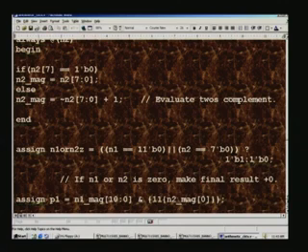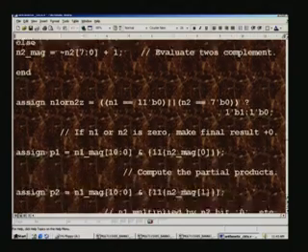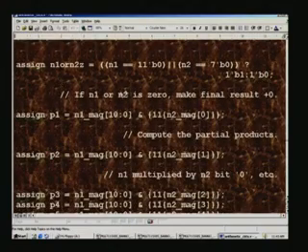And these are all basically combinational circuits, and this is also another combinational statement, wherein we inspect whether n1 and n2 are zeros. Even if one is a 0, the final result is going to be 0, and if you do not take this, you may get into problems later on with the finite fixed point arithmetic which you are dealing with.